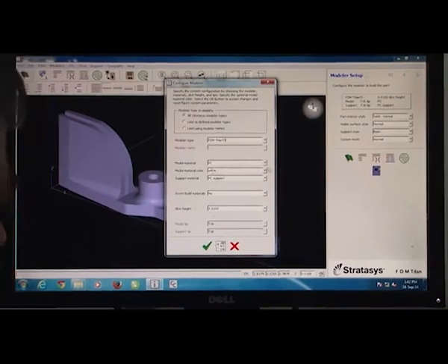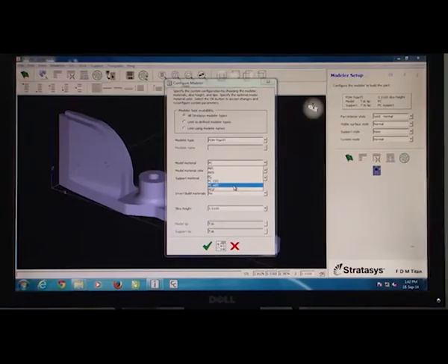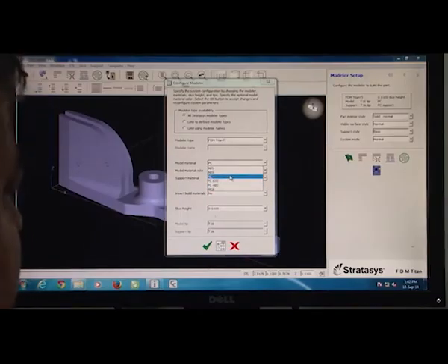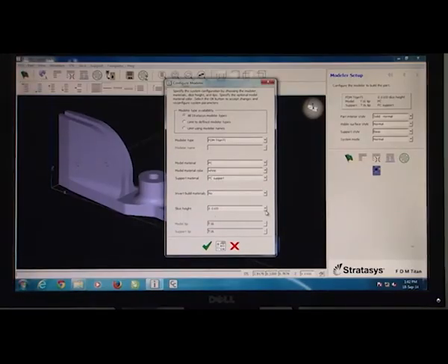The different materials again, so in this case it is polycarbonate, but there are ABS materials, there are a variety of different even polycarbonates, okay, which are available. In this case we want to choose a simple polycarbonate PC, okay, so it is demarcated by PC. So we are going to take this up, okay. Now my model automatically, the model material color is defined as white in this case.